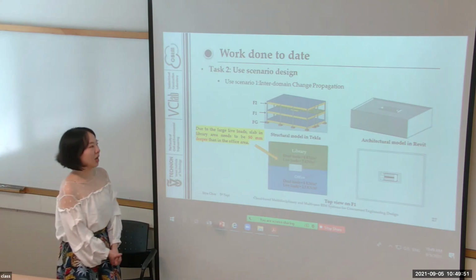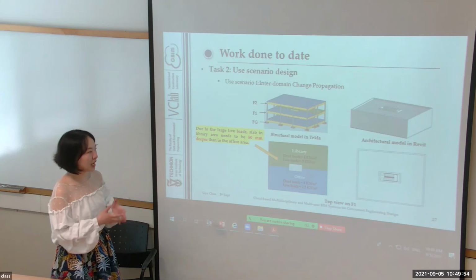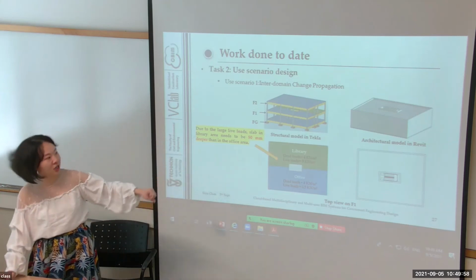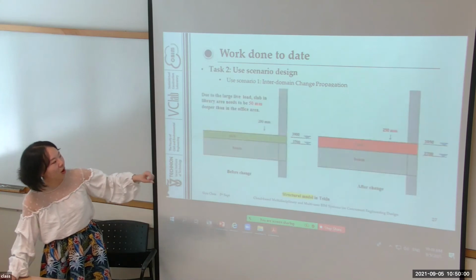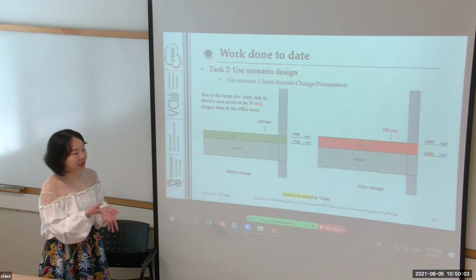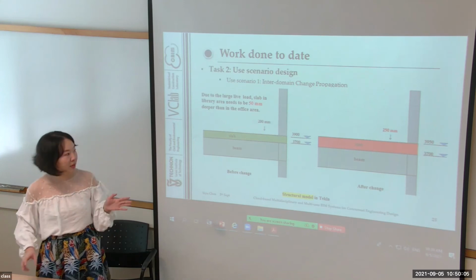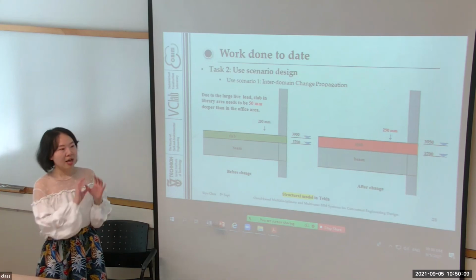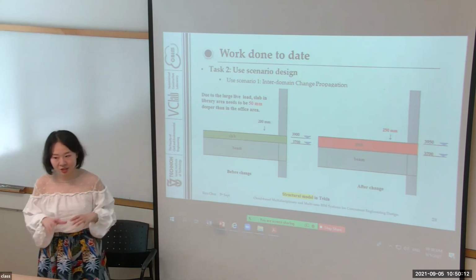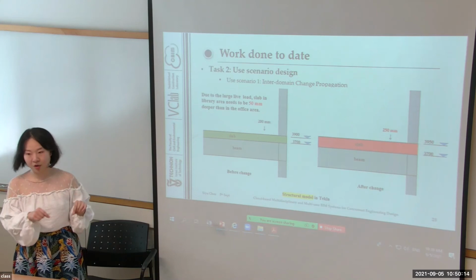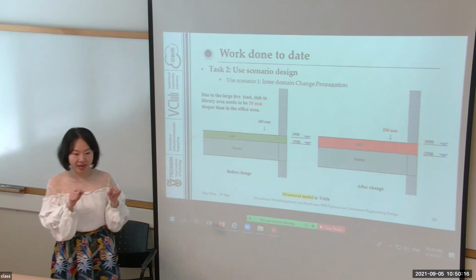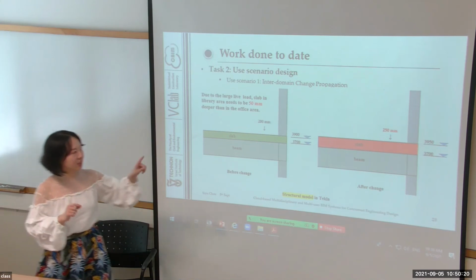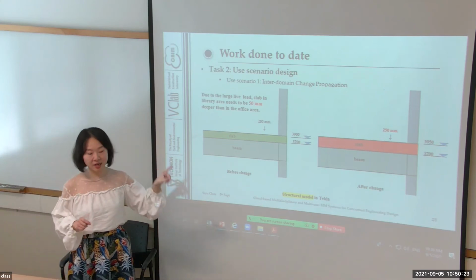So the structural engineers split the slab into two parts, as you can see in the picture, and also made the slab thicker upwards by 50 millimeters, as you can see in the right-hand side picture. So far, the changes in the structural model have been done, and saved with temporary status. Remember, temporary, because this change is related to the architectural model.